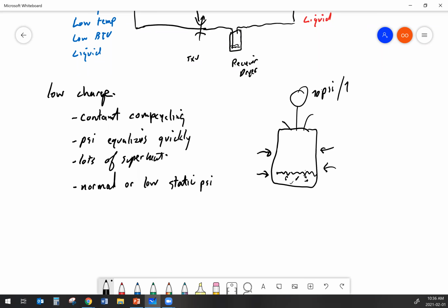Now with 134a, it's roughly 70-70. So at 70 degrees Fahrenheit, you should have about 70 PSI. I think the actual number is like 71 point something, but 70-70 is really easy to remember. Okay. So at a comfortable room temperature, you should have about 70 PSI of pressure in your refrigeration system.